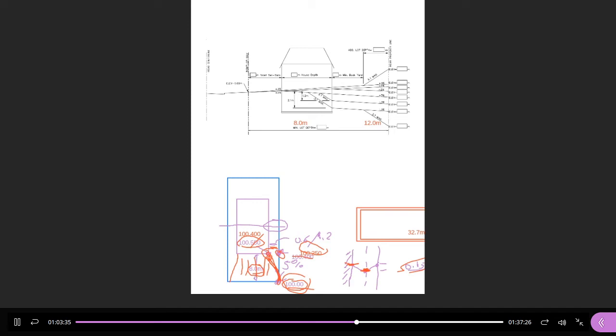Suppose we don't need 3%. Let's use the minimum. Instead, let's use 2%. Start at the front and go all the way to the back at 2%. That's the next scenario. So then you would be about 0.65 above. It might be confusing, so I'll put it up here. Okay. So if you come up at 3%, you're 0.98 above the front. If you come up at 2%, you're 0.65 above.